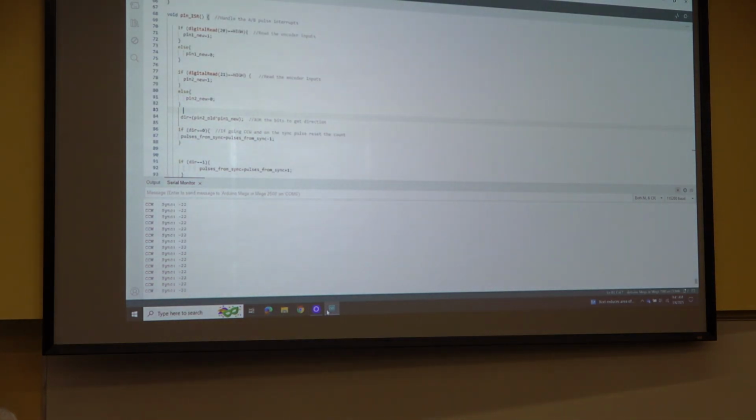And if I reset my Arduino, I do have a problem. This was running perfectly on my kitchen table last night. For some reason, it's going to 0 on startup. If you start your encoder, an incremental encoder, you have no idea where it is until you go around and you hit that first sync pulse. Then you can start counting and get position.